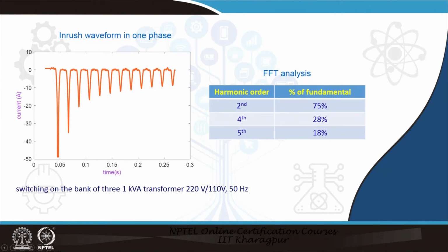So, this reveals that if this amount of current, which happens to be maybe more than 5 times the current in one of the phases, flows, then it will operate the differential relay. Therefore, in this relay experiment the settings to restrain the relay and block the relay operation are accomplished. In this particular experiment we have a second harmonic restraint, which is a particular setting, and that is decided by the operator as per the requirement.